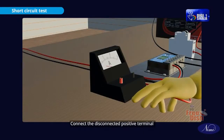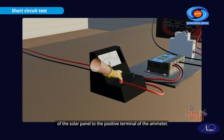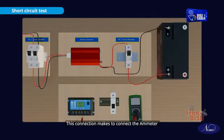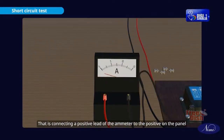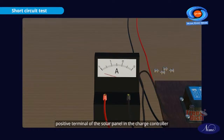Disconnect the positive terminal of the solar panel from the charge controller. Connect the disconnected positive terminal of the solar panel to the positive terminal of the ammeter. Now connect the negative terminal of the ammeter to the positive terminal of the charge controller. This connection puts the ammeter in series with the solar panel and the charge controller. That is, connecting the positive lead of the ammeter to the positive on the panel and the negative lead of the ammeter to the load via the charge controller.